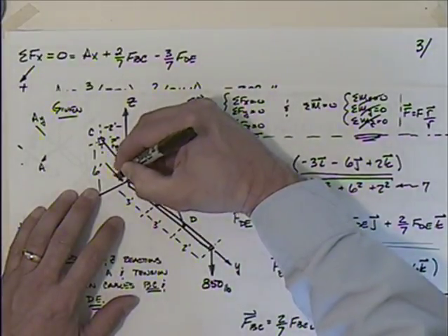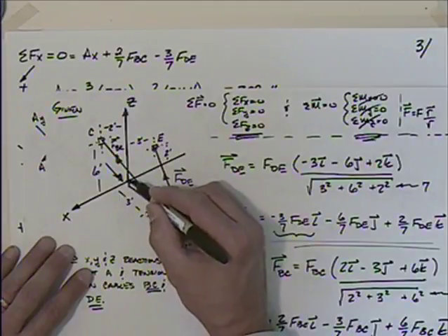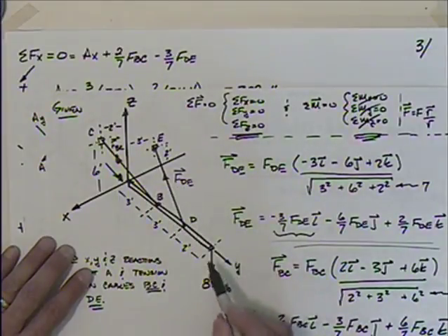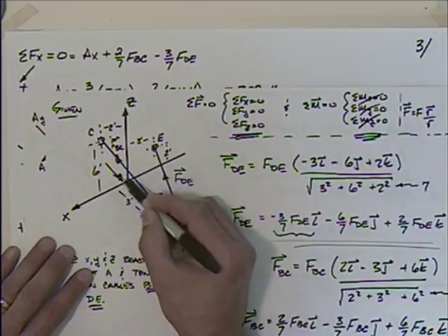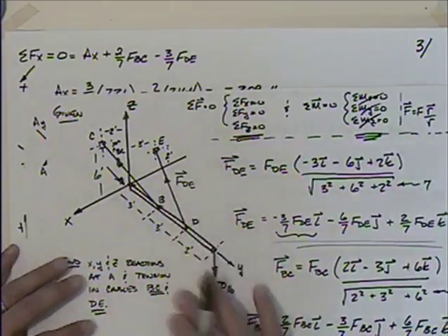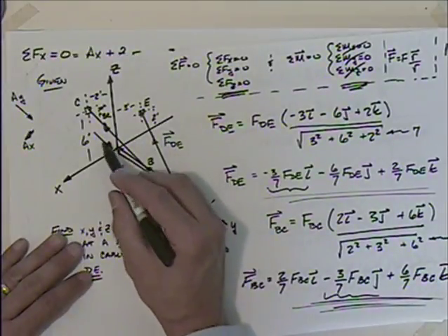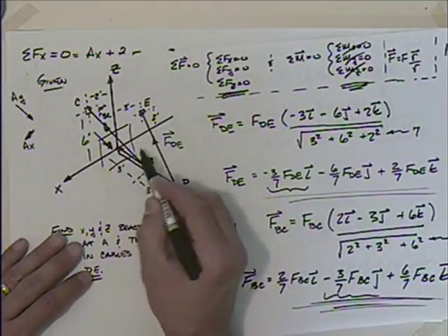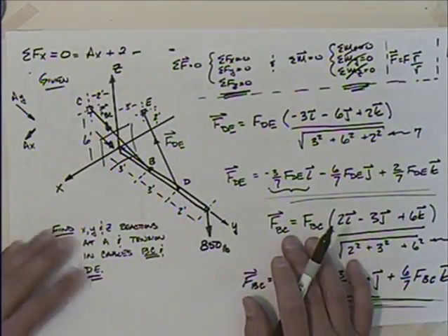Really, that's the force there where if this was some brick wall and we were putting a temporary crane or something on it, that's the force that's trying to push a hole in that wall, 1545. So that would be good for design. Maybe we'd have to put some sort of a reinforcing plate in there. You don't want to punch the crane post right through the brick or something like that.